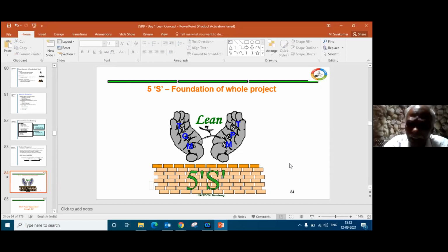No, customer satisfaction is very important because what the customer wants decides the rate at which I'll have to produce. Understand? So customer demand is the denominator. Very important. The rate, the speed with which you should produce, is to deliver the item exactly on the targeted date, which is set by your customer. If your cycle time is more than the takt time, your delivery is definitely going to be delayed. If the actual cycle time is less, then deliveries can happen earlier.